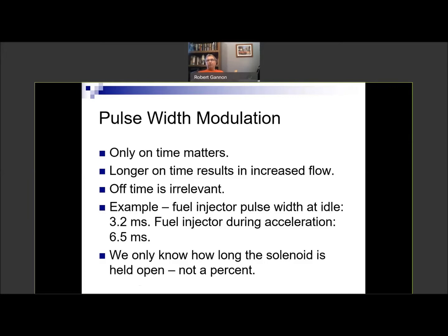In the lab, I don't know whether you've seen it or not yet, I showed fuel injectors, and we were measuring the fuel injector pulse width. And pulse width is just a fancy term. Why they say width is, I guess, if you look at it on a scope or on a graph, the length of time it's on is a line going across the screen like this. So how wide is that line? On the oscilloscope, we saw that line lasted 2-3 milliseconds. So the pulse width is 2 or 3 milliseconds on that injector.